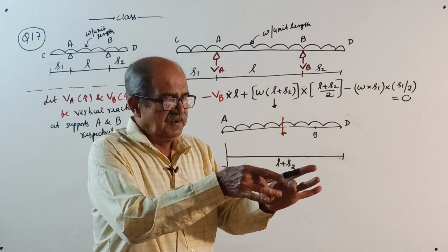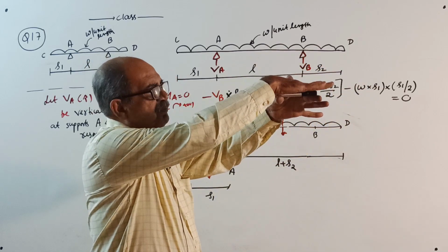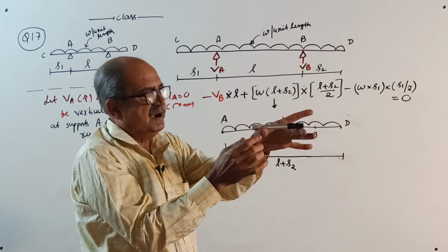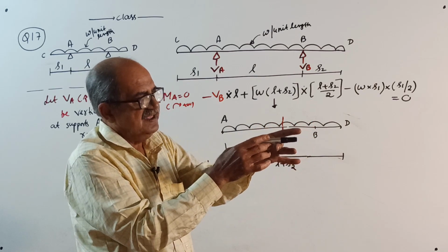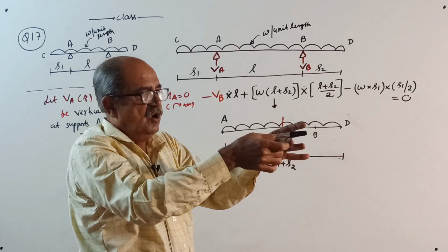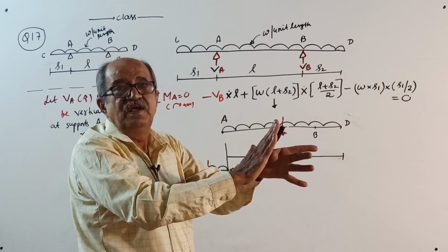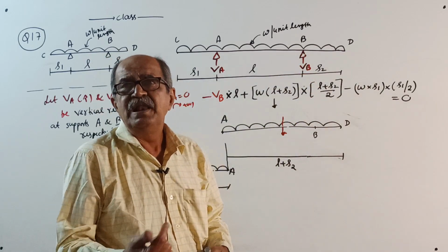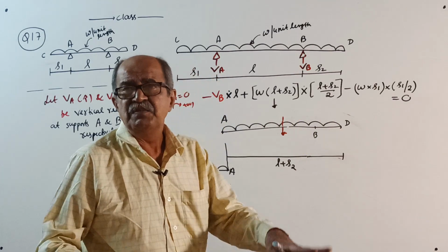Now, suppose the beam is this way. Suppose you have small overhangs. When you apply load, this loading will press the support down, both reactions will be up. But suppose you got more overhang on one side and less overhang on the other side. Now when you apply the load, this support will get lifted. Or if you got more overhang on this side, then when you apply the load, at that support the beam will get lifted. So when lifting comes, you require downward reaction. That all will vary in the principle as time comes.